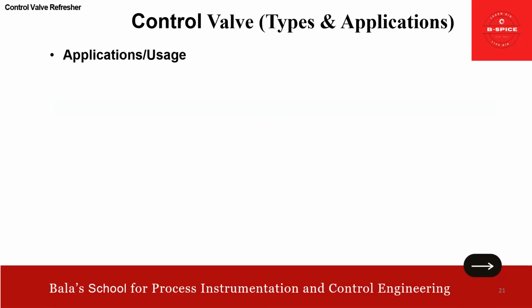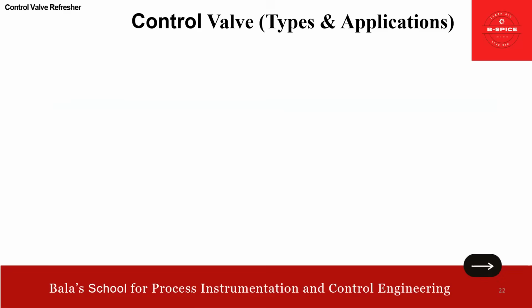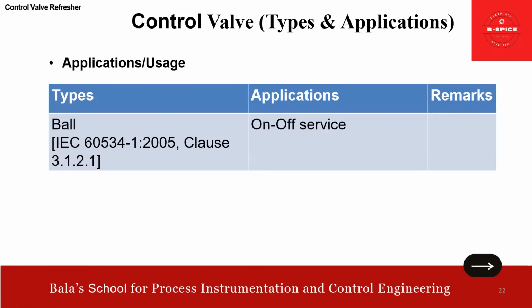Then we talk about the three-way valve. It's very simple: for diverting and mixing services. Then we have the ball valve, which is in compliance with IEC 60534-1:2005, clause 3.1.2.1. This is predominantly used for on-off service.